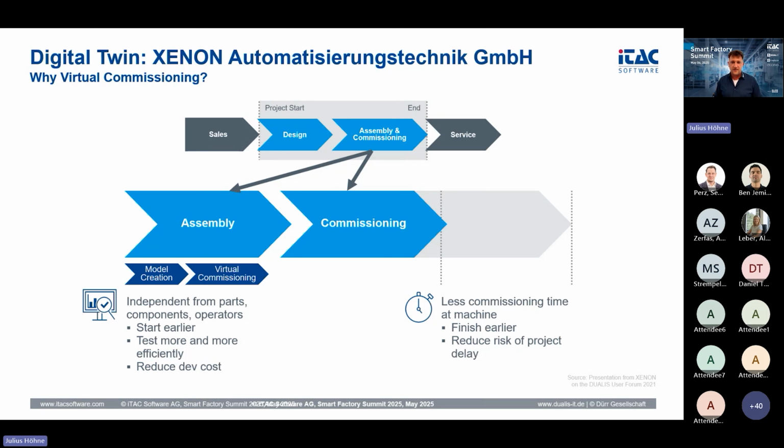After we have successfully done the virtual commissioning, and all of our processes have been thoroughly tested, we come to the stage of the real commissioning. Now we can load the PLC program into the controller and we can start the physical system. And once the machine is running, we have a bidirectional connection between the real system and the PLC. That means the system sensors can send real signals to the PLC, which processes the information and sends control commands back to the machine.